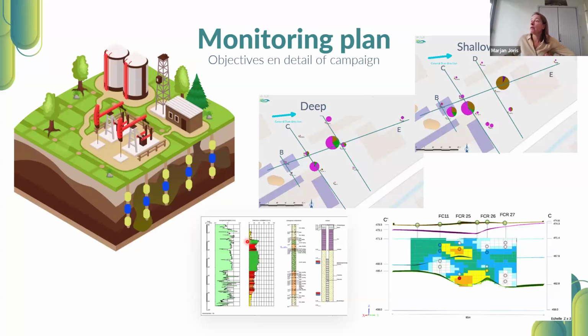The selection of the wells as well as the depths was done based on the HPC drilling performed before the iFlux campaign. And here we could see that the upper layer was less permeable than the deeper layer, but concentrations in this layer were higher. That's why it was chosen to measure in both, to better understand the mass discharge and the spreading of the contamination in both layers, for example.